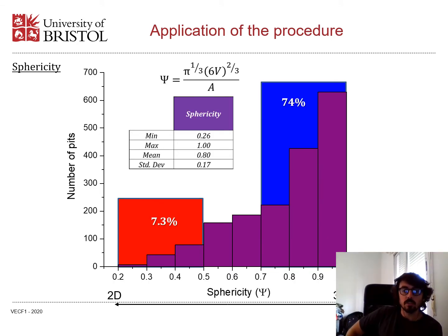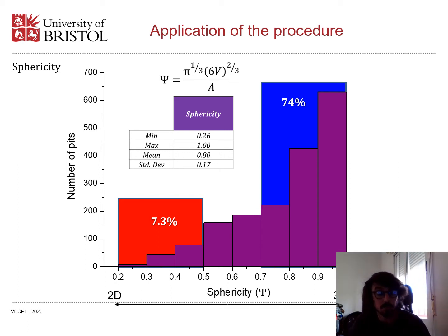Once we calculated sphericity for all those defects, we realized that unfortunately most defects were quite blunt and quite volumetric. So from a sphericity perspective, the least number of defects were considered more severe, but there's also a need to understand how those defects were located in the structure and how large the size of these defects was.